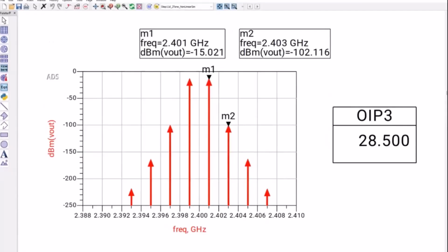So, okay, how do I add a boundary to the overall layout design as you have added? I'm not pretty sure. I didn't add any boundary. It's just the copper boundary. Shall we try to have 3D shapes of discrete elements? It's not required. 3D shapes of discrete elements are just visualization if you want them, but frankly speaking, it's not required. 3D simulation doesn't mean 3D SMT model. 3D simulation only simulates your PCB and the copper trace and everything. Anyway, no EM simulator simulates your SMT device.